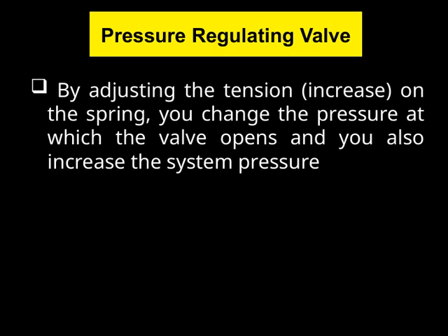This adjustment not only controls the opening point, but also leads to an increase in the system pressure overall. So, by tuning the spring tension, you can precisely regulate the pressure within your system, ensuring it operates within safe and efficient parameters. This is a key concept because it highlights how pressure regulation can be customized to meet specific system needs, maintaining stability and performance throughout the process.